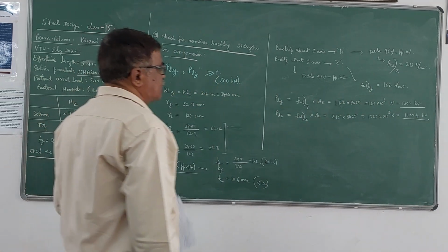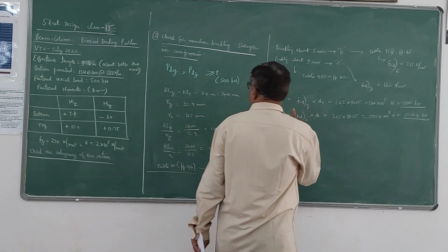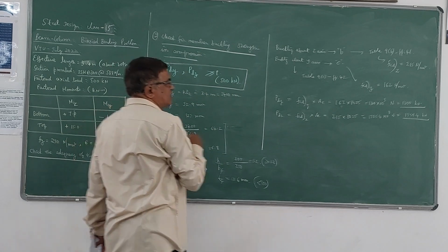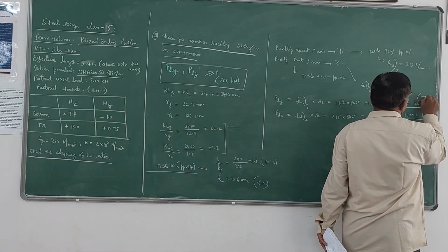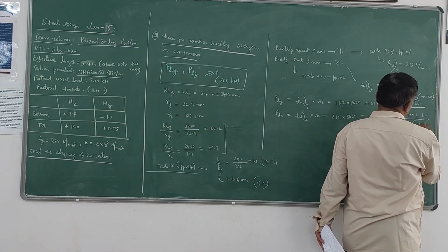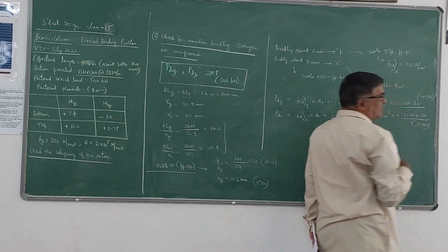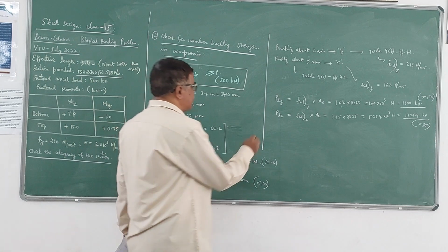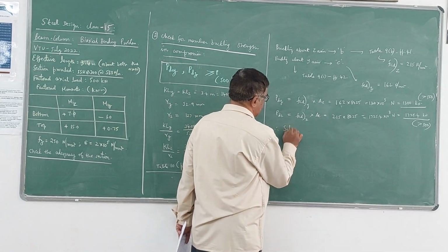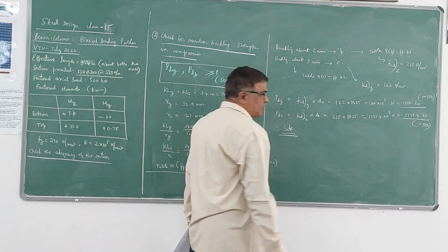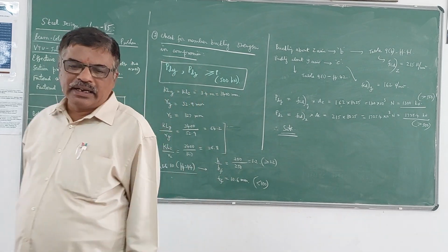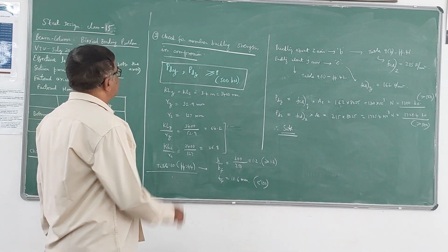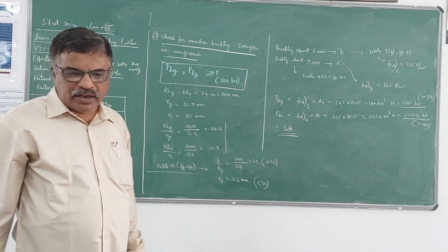So these two are the values of PDY and PDZ. You can observe here both these two are greater than P. So this is also greater than 500. This is also greater than 500. Therefore, the strength is more than the axial load. So therefore, you can say that it is safe against compression. So that means that the beam column, whatever is given, is safe if it is treated independently as a column. So this is the second check we have to carry out.